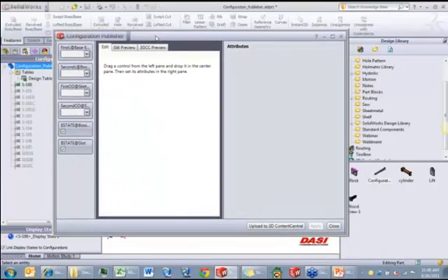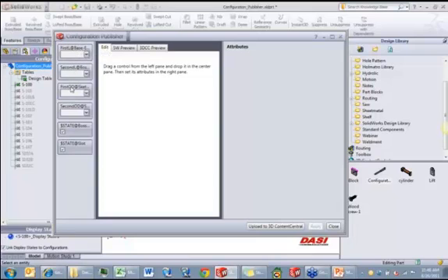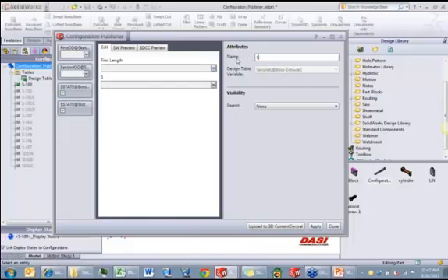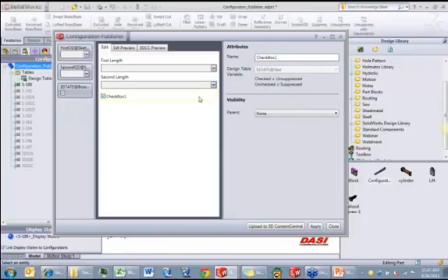It can't be manually created configurations. Now, you've got the dimensions that are in the Excel spreadsheet, those columns, and that's why I think you have to have a design table. Now, you can drag and drop those dimensions in whatever order you want, and I can give these names. Let's see, first length of the shaft, then we can also go with second length. And you don't have to put in all these variables. You can just do 3 of them. This is whether I want a slot or not.